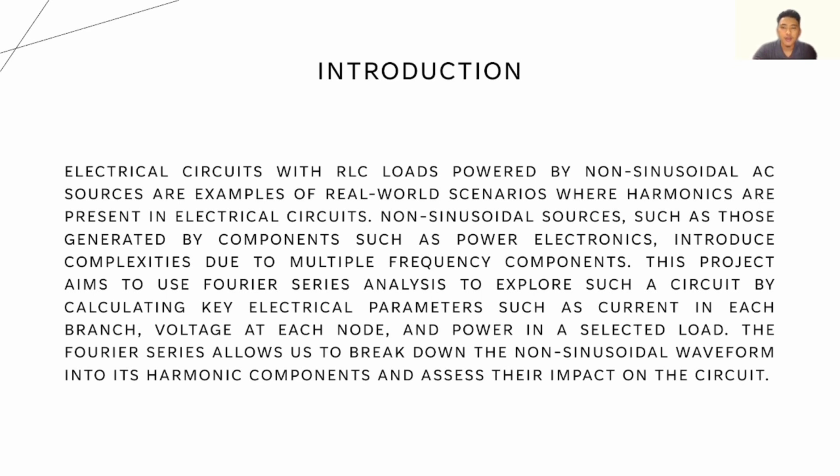The aim of this project is to use Fourier series to analyze the circuits by calculating electrical parameters such as current in each branch, voltage in each node, and power in a selected load. The Fourier series allows us to break down the non-sinusoidal waveform into harmonic components and address the impact of the harmonics on the circuit.